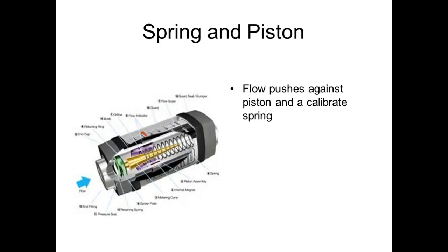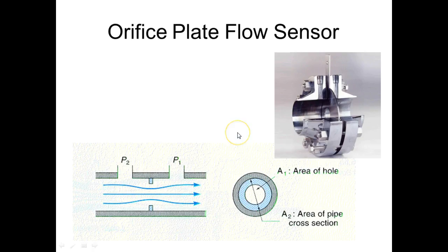If I needed 100 psi at a certain flow rate at my actuator, then I'm going to have to calculate what pressure I actually need on the input of the system to get that pressure out and regulate the flow. That would be engineering. Odds are you don't have to worry about that. It's just that if you're a technician and you're going to replace one of these things, you need to get the part number and look at the pressure differential and the port sizes, and make sure you get one with equivalent port sizes, and then flow rate. So hopefully you can see the way this thing works.